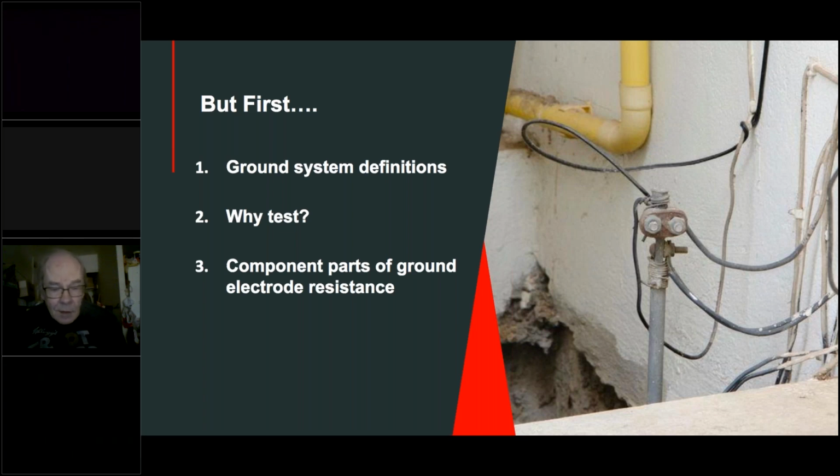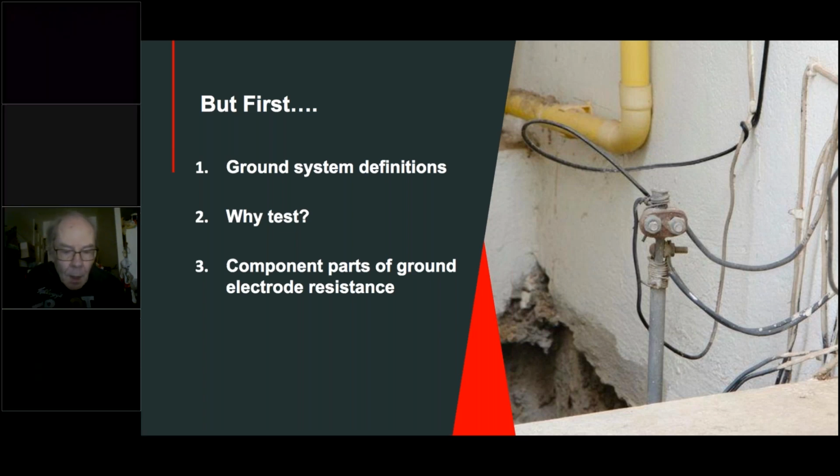And keep in mind, that's there to divert currents into the ground that you don't want in your electrical system. If it's a lightning stroke, then the gradient on the earth evens up with the gradient in the clouds, and that's what becomes of it. If it's a utility fault, then it's got to go back where it came from, which would be the utility generator that services your site. Okay, next.